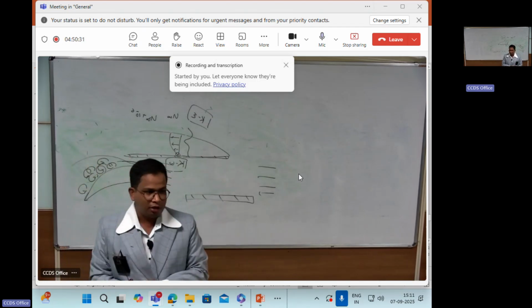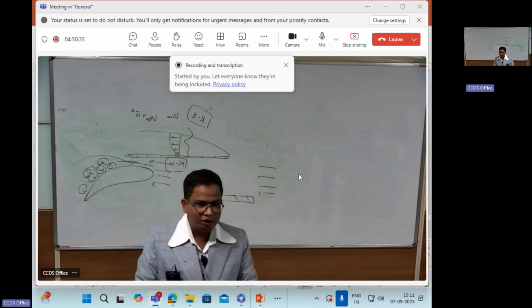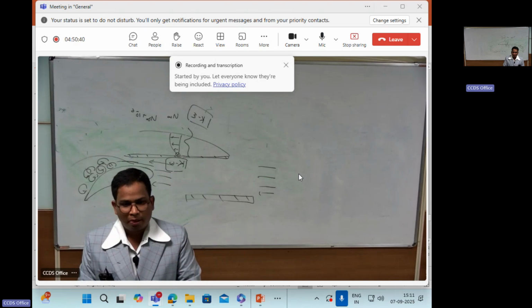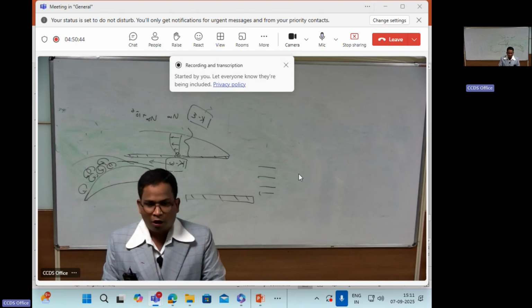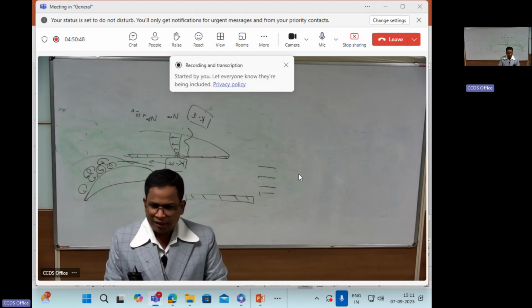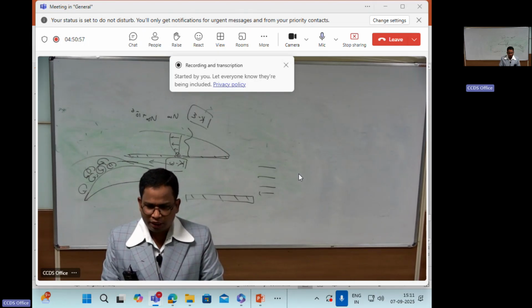This session will cover large eddy simulation. Yesterday in the introduction session, we understood the scales associated with turbulence. If we are resolving up to the smallest scale, that kind of simulation is called DNS, and it is usually quite expensive. The computation takes a long time, and for engineering calculation it's not feasible.